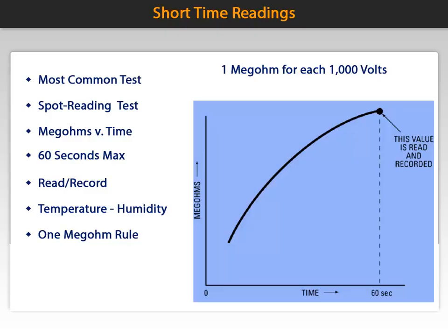By recording these measurements over time, you gain a better basis of judging the actual condition of the insulation. Any persistent downward trend is usually a warning that there's trouble ahead, even though the readings may be higher than the suggested minimum values. Periodic readings found to be lower than recommended values may be okay as long as they are consistent. Refer to the ANSI/NETA maintenance testing specification for recommended insulation resistance levels in the absence of manufacturer standards.